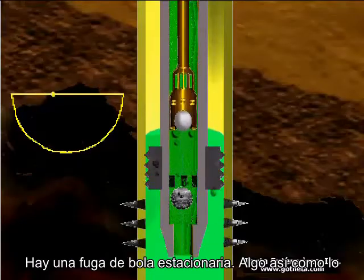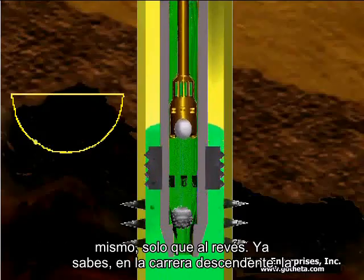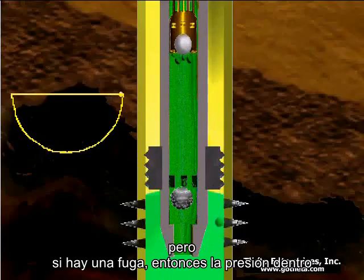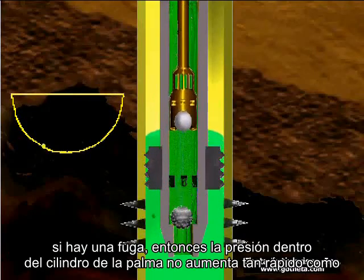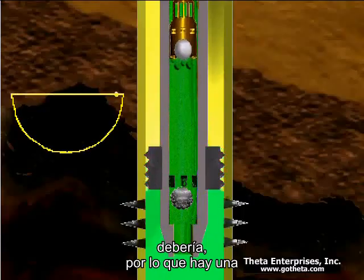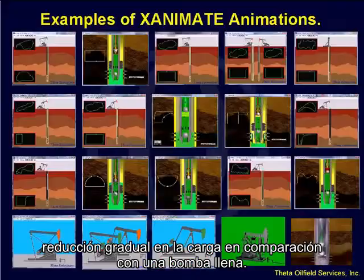There is a standing valve leak, kind of the same thing, only reversed. On the downstroke, the fluid load is being put on the standing valve, but if it's leaking, then the pressure inside the pump barrel doesn't go up as fast as it should. So there's a gradual reduction in load as compared to a full pump.